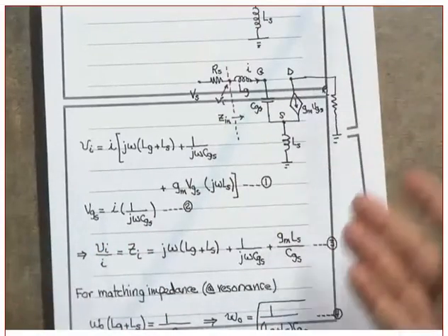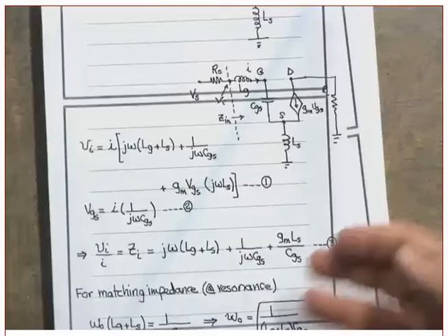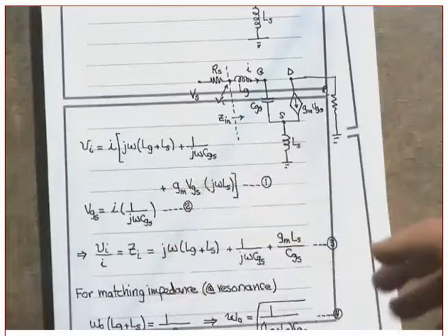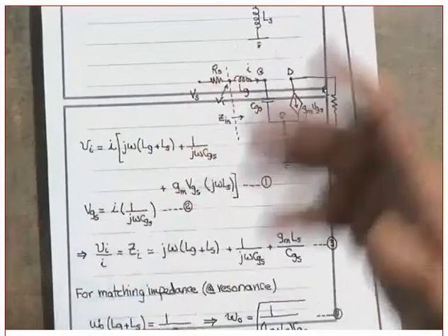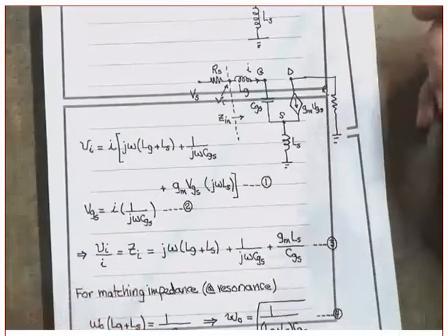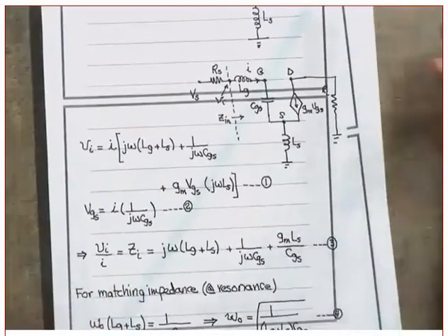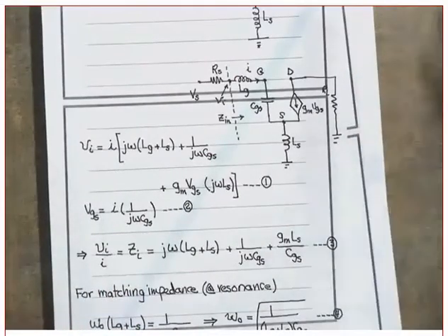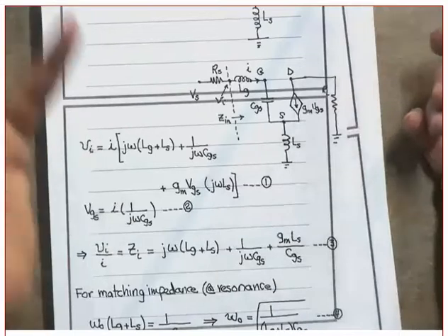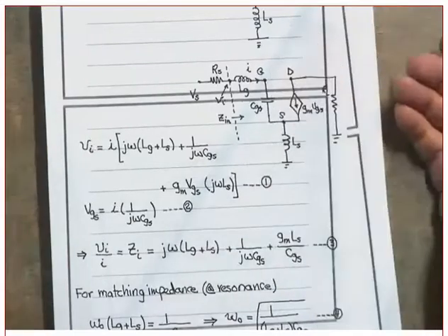Now, this is theoretically speaking. In reality, you are going to have some parasitic or internal resistances inside those inductor and capacitor, which will introduce additional noise. But theoretically speaking, it should not have any effect on the noise figure because it's not a resistive element. Capacitive. The gain of the amplifier will perform badly if... actually, the gain will increase. I will show you that because we have a resonance circuit here.